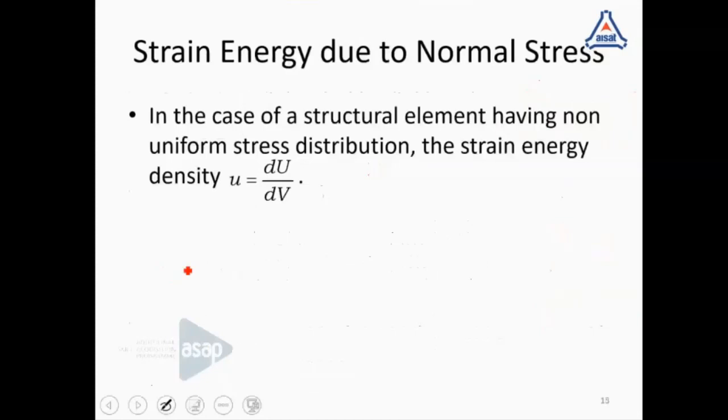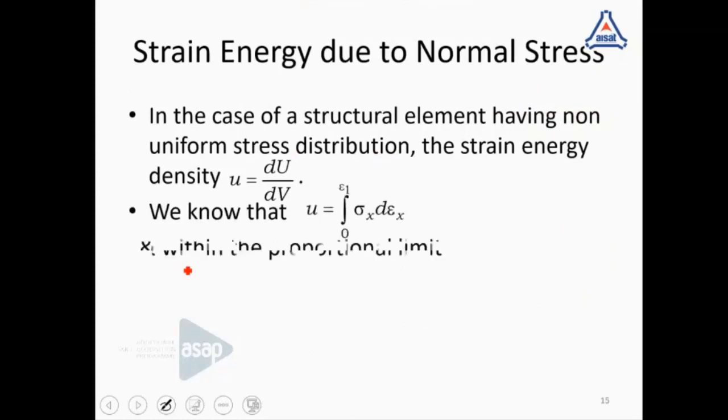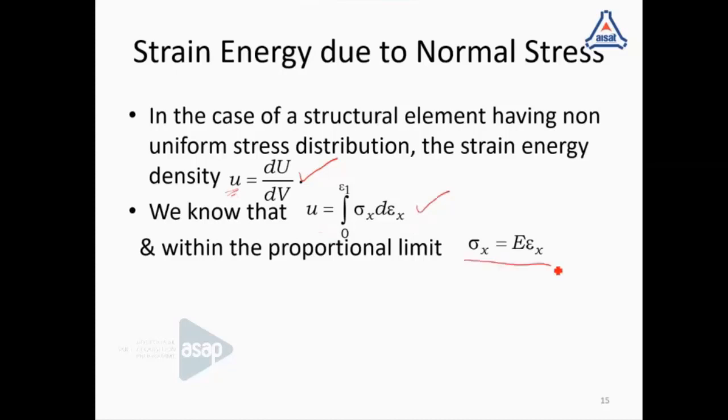We can see how the strain energy due to normal stress can be developed. So this is a basic expression for elastic strain energy density, and this expression we already have seen. Within the proportional limit, this expression comes from Hooke's law.